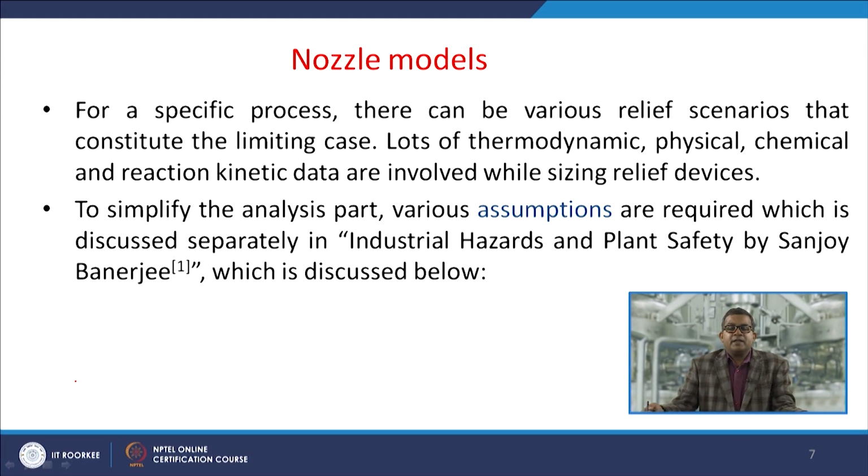Whenever we are discussing this aspect, we should give due care to nozzle models. For specific processes, there can be various relief scenarios that constitute the limiting case. Lots of thermodynamic, physical, chemical and reaction kinetic data are involved in these relief devices.